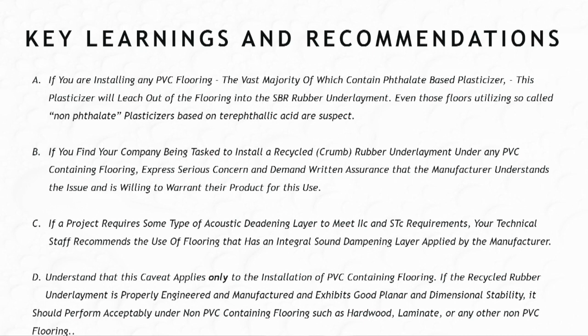Now, understand this, and this is extremely important: this caveat applies only to the installation of these materials over PVC containing flooring. I'm not impugning this stuff. It makes a wonderful sound deadening material if it is dimensionally stable and has good planar stability. In other words, it doesn't get bigger, doesn't get smaller, doesn't curl, doesn't dome, doesn't just go crazy moving around.